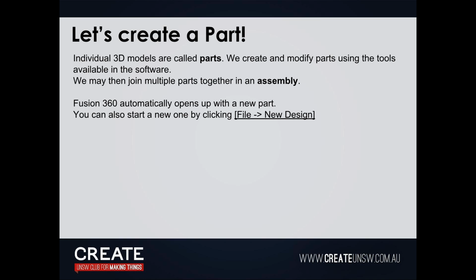Right, we'll get started in here. Just a quick overview of this interface. You have your basic sketch tools: line, rectangle, circle. We'll get to those individual tools in a second. You have Create, this tab, which is mainly for 3D, which we'll get into next week. Modify is pretty much for 3D as well. Assemble, all these are mainly for 3D. Inspect is just to check the dimensions and sizes of multiple parts. Insert is a very useful tool. If you have an image like this, for example, you can project your model onto an image and vice versa.